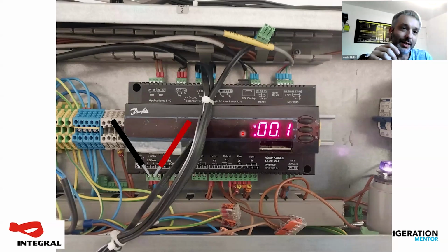And we actually talked about this last night, didn't we, Trevor? If you just touch the top button on the controller, it'll give you a status code for what the controller's doing. You want that to be telling you that it's in regulation or startup. If that's giving you an alarm code straight off, or a status code saying it's stopped, then you know where to look around the rest of that controller.